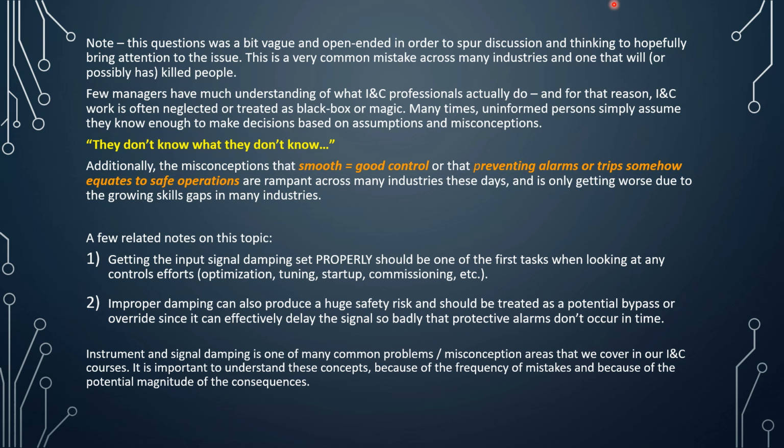And I've seen scenarios where 60 seconds of damping was set in a level safety transmitter for an unknown amount of time. No one knows how long it was there, possibly years. That's a scary thing to think about on a level safety transmitter. That's your only protection. There's no PSV. There's no other safeties that you're counting on to protect you. Luckily, they didn't need it.